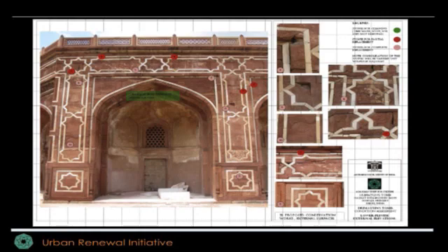A lot of this deterioration really happened on the lower plinth, and this happened because of two reasons. One is that water was percolating, and the second is that the joints of the stone had been filled up with cement. Now this is very basic common sense more than science. One of the principles of conservation is that whatever new material is added should be weaker, lighter, and sacrificial.